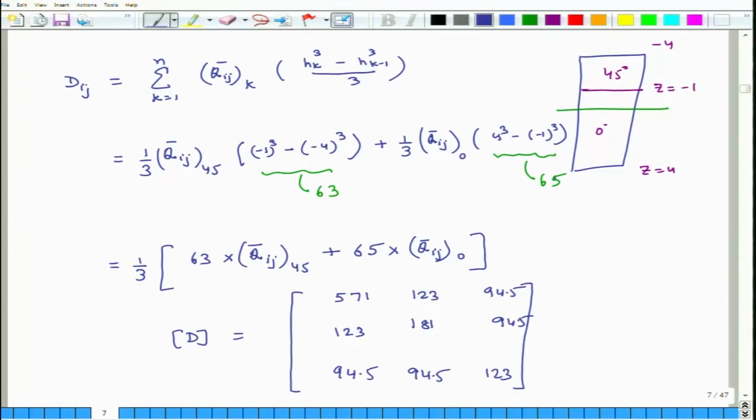So, these are our 3 matrices A, B and D, and I wanted you to see how these matrices are calculated. Now that you have the method, which I have explained for any laminate, you can use this approach to create A, B and D matrices, and using those matrices you can do further computations. This is what I wanted to cover in today's discussion.